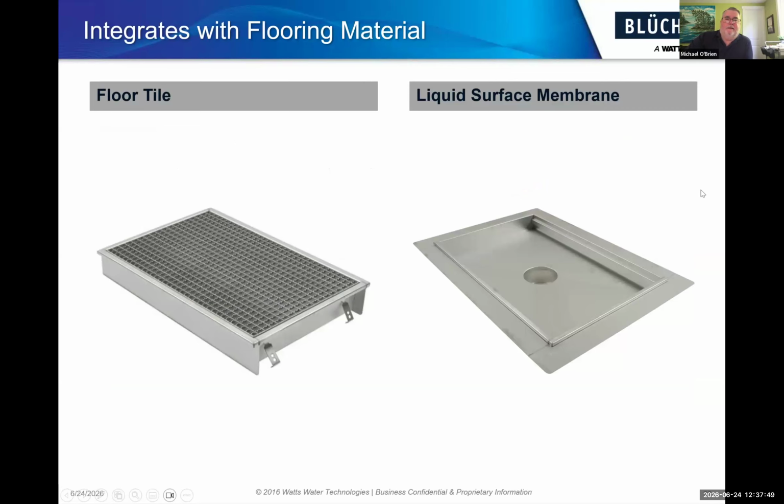And with different ways to integrate with the floor, this gives you a tile edge to butt tiles up to. The one on the right is for a liquid surface membrane, so this drain would get installed, and then a liquid would be rolled over top before placing a tile, or they could use that with an epoxy or a urethane.